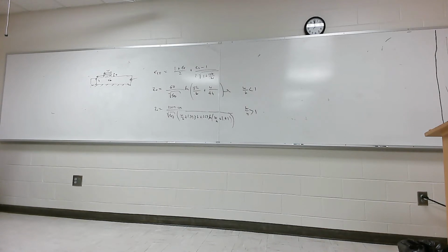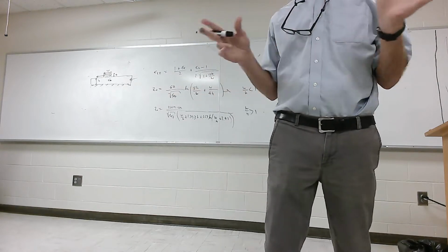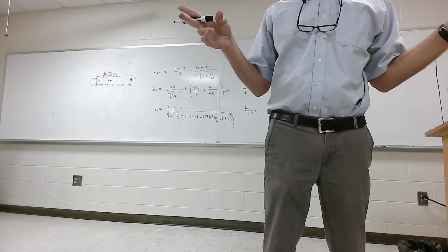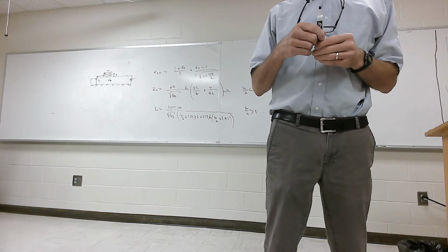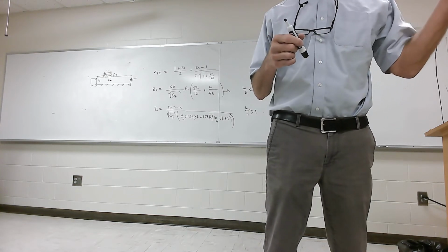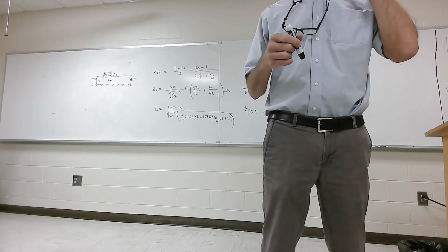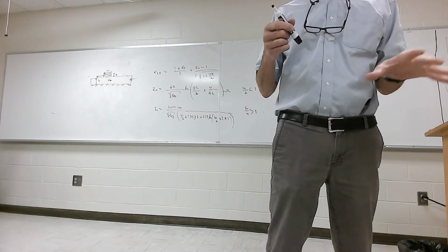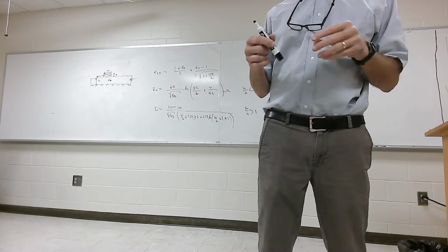And some of you are going to be doing this stuff for a living, so hear me on this. Duroid board is expensive, very low loss. It's the best thing to use, but don't use it unless you have to use it. That means if you're up around gigahertz, you need Duroid board. If you're at lower frequencies, hundreds of kilohertz, even up to probably 250 megahertz, you can get away with that green FR4 board. Now, do you all know what FR4 board is, most of you? Duroid board, if I find a piece, I'll bring it down here next time. I don't know what happened to it in my office, but it walked away. Somebody probably used it. But you should at least be aware of these things.